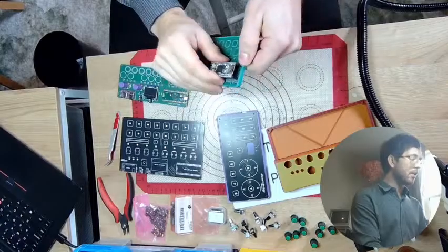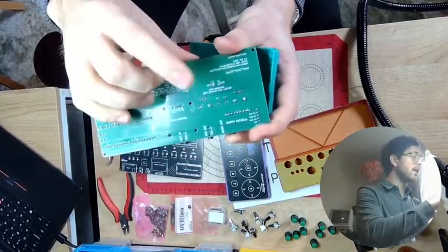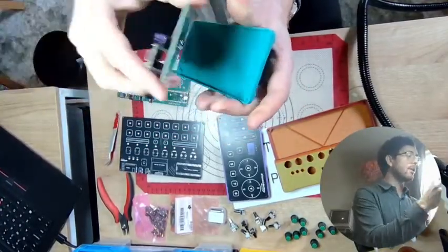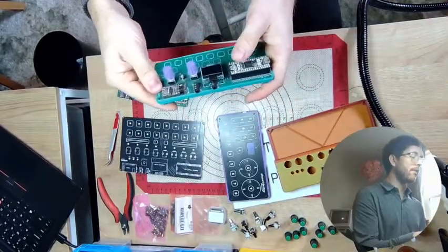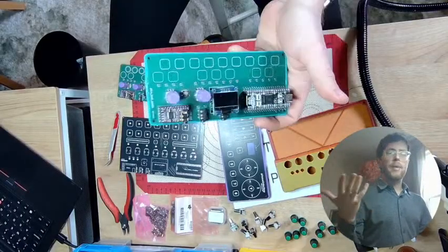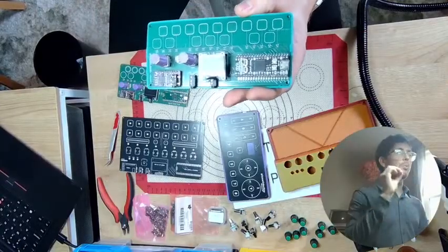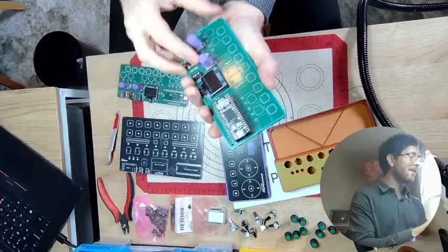And you'll notice with this one, we actually have to switch between 3.3 volts or ground as that sink. And the reason why is because when the RP2350 came out, it had an errata, E9 or something. I can't remember. But basically, it doesn't pull down super well, so you have to pull up instead. I don't know. It's super weird.